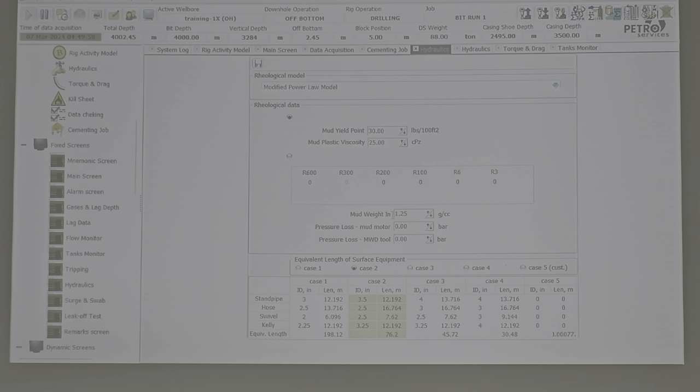Okay. Here, in these three items, we have one way. Of course, if you have a sensor, this is easy and will be hidden, because the sensor changes it automatically. But in the normal situation, mostly we don't work with the mud weight sensor, because you need to keep it clean. If you leave it for two to three days, some cuttings will accumulate and it will give bad values. If you work with a mud weight sensor, you have to clean it regularly. If you do not, you just put it manually and get it from the mud engineering report.